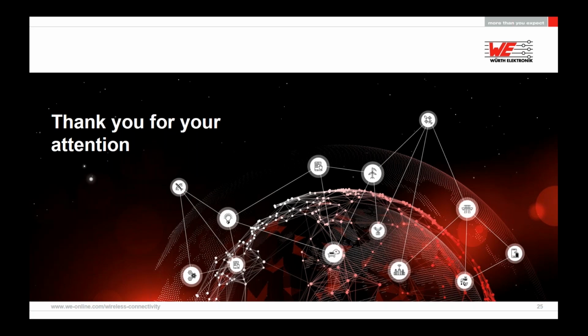Yes, so our modules are pre-certified for the European market with the CE, or the RED, its radio norm of the CE. Also for FCC, the USA, IC, Canada, and for a few cases also for the Arab and Japanese markets. Meaning that if you integrate our module in your end device, only for the CE and only for the FCC, the measurement of the unwanted emissions has to be done in the end device. For the IC, Canada, and also for the Arab and Japanese markets, no measurements are needed for your end device. So you can plug the module into your end device and use it.